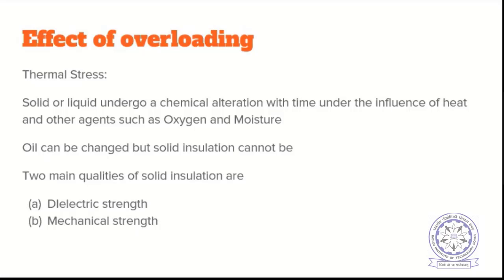But out of the solid or liquid, we don't have much problem with oil, because oil can be changed on a particular schedule, or whenever you feel that oil has deteriorated, it can be replaced. It's not a problem. But solid insulation, which is supporting the windings or winding structures, is not easy to replace. You have to rewind, that's it. So this is difficult to replace.